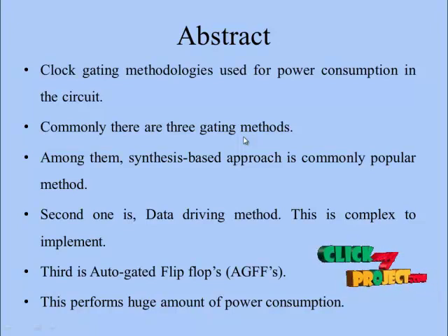So pulse triggering, which is one of the single-latch structures, is more popular than the conventional transmission gate (TG) and master-slave flip-flops in high-speed applications. Besides the speed advantages, its circuit simplicity lowers the power consumption of the clock tree systems. A flip-flop consists of a pulse generator for strobe signals and a latch for data storage.